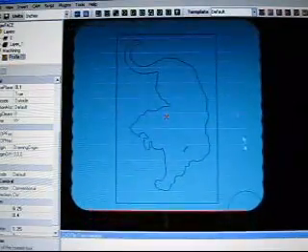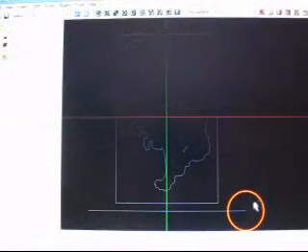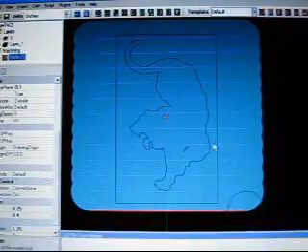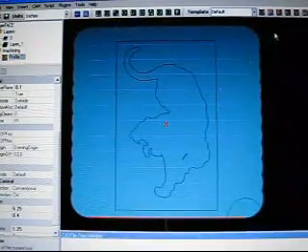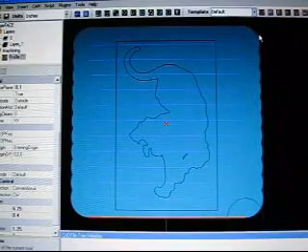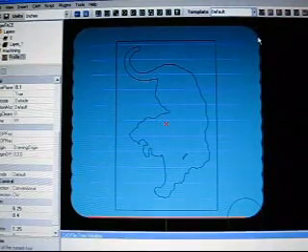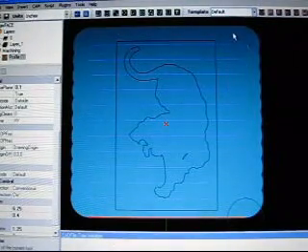So this is just like I was showing you the width of this diameter, just so I drew that little thing so you could see. Now this shows you the cut width, your actual cut width. It's kind of like you're verifying how much material you're removing, because it shows you the diameter of the tool, not just the toolpath itself, not just the actual center line of the toolpath. It's showing you the diameter, which is useful information. You want to keep that in mind.